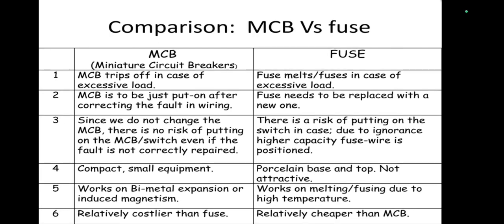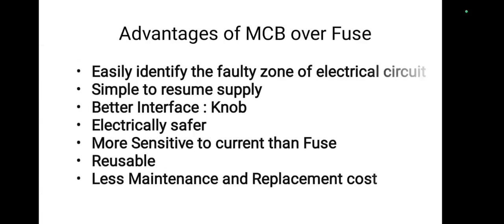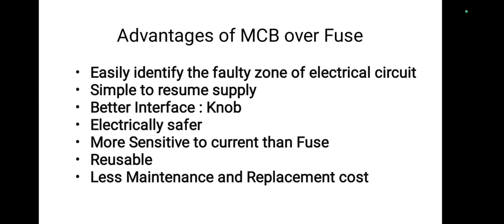Now we are going to discuss the last topic, which is advantages of MCB over fuse. MCB easily identifies the faulty zone of an electrical circuit, is simple to resume supply, has a better interface, is electrically safer, more sensitive to current than fuse, reusable, and needs less maintenance.